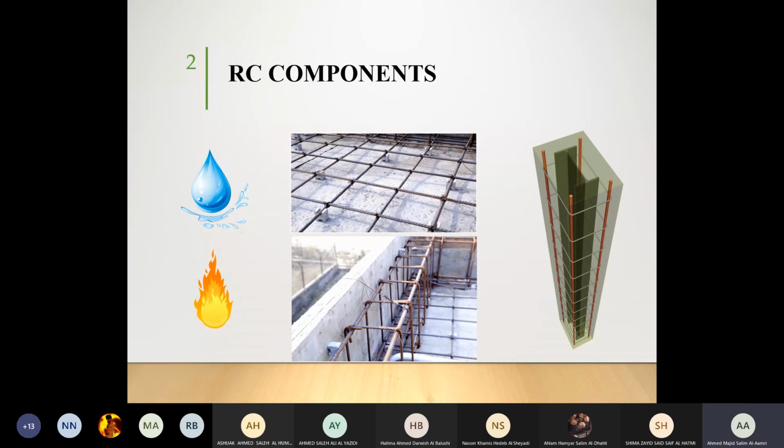Now, for example, when it comes to a hospital, when it comes to a mall, a lot of people are there, so it requires more time for evacuation. In that scenario, you need to take more fire resistance hours for the design. Are we clear? Yes. So it's not possible that you are going to make your steel protected forever, but this fire resistance protection is going to ensure whoever is inside that particular building can be evacuated without severe issues. Are we fine? Yes, Mr.